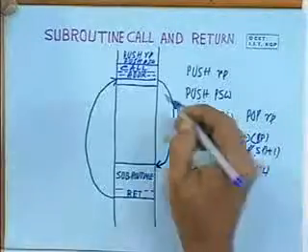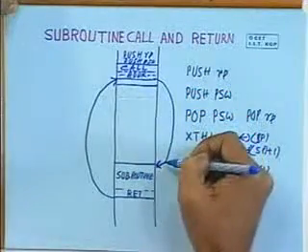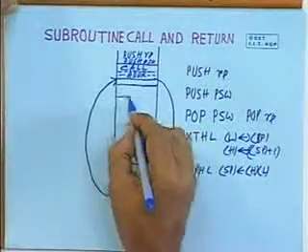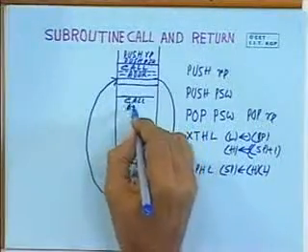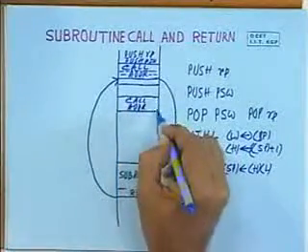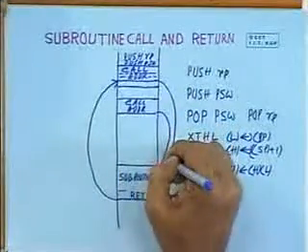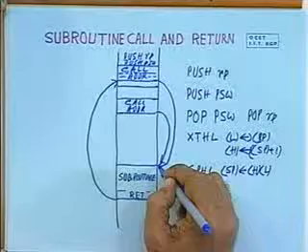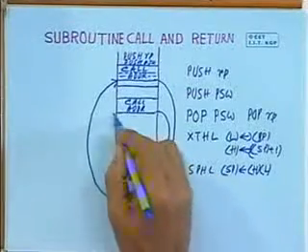Now it may be necessary that, suppose you have performed one instruction execution, there may be another call of the same subroutine, say call address, before you have returned back. So in that case again it will go back to this point, and after the execution of this it will return here.